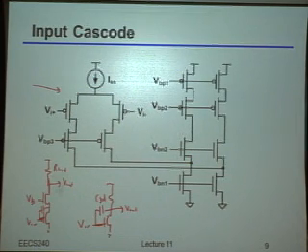So again, the really critical thing to remember is that just because you have a cascode does not mean that at the end of the day you have a low impedance at that node. Because you always only get a gmro of isolation there. So in this particular example, because the load itself is very high impedance, that therefore means that I still actually have a high impedance here.